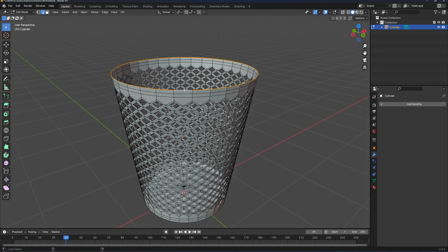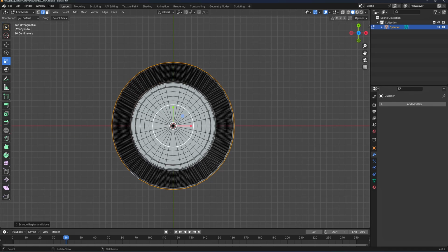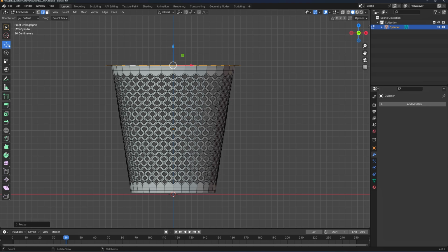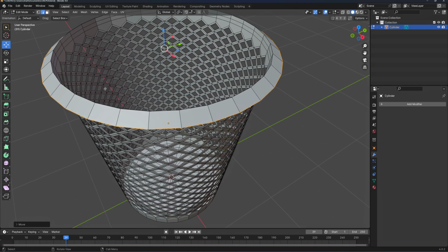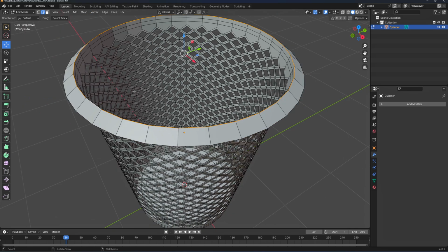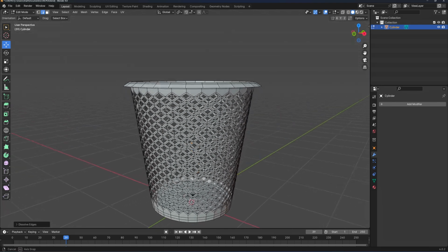Now I'm going to select that edge loop here to extrude, left click, going to top view here by pressing 7. I'll go ahead and scale that bad boy up here a little bit, and front view here, I'll go on my move tool. I'll drag that, simple drag. Now we're gonna be looping that with Shift here and Alt, right click and bevel the edge. There we go. Now we end up with that shape here, and it's quite nice.